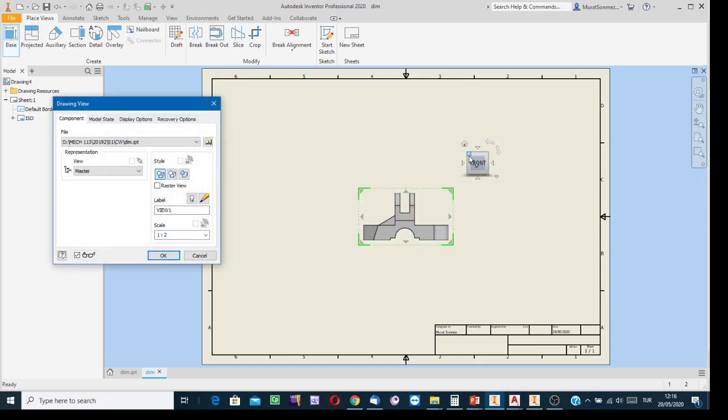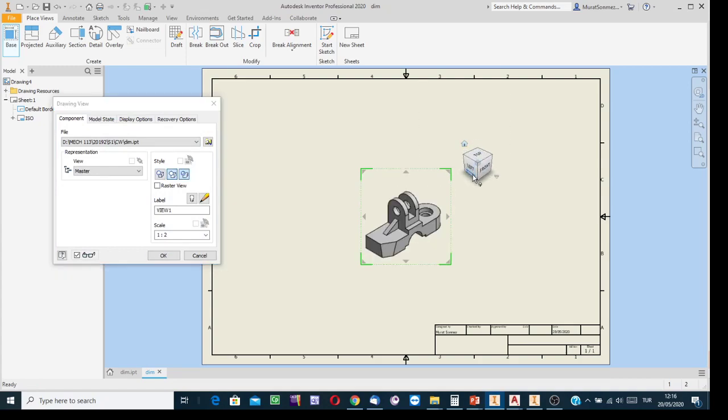Teach the software which side is the front side. For your convenience, to see the model pictorially, click on the house symbol and then fix the home positioning of the solid model, so you know which side is the front side.